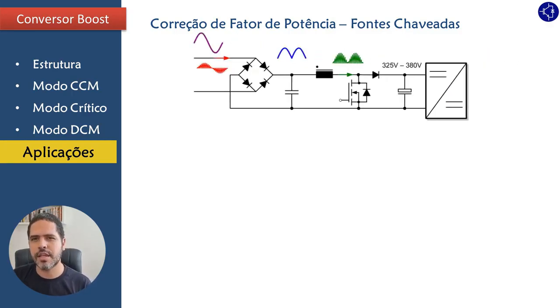It's basically this generic diagram here, right? So instead of having a rectifier with a very large capacitive filter, which causes the input current to be very pulsed, I'll use a rectifier with a tiny insignificant capacitor that doesn't make much of a difference. This makes the output voltage of this rectifier have that full wave rectification shape, right? Yeah, and I add a boost converter that will control the current in this inductor so that it has the same shape as the voltage at the rectifier output. If I can do this, when I look at the grid, my current will have a switched sinusoidal shape.